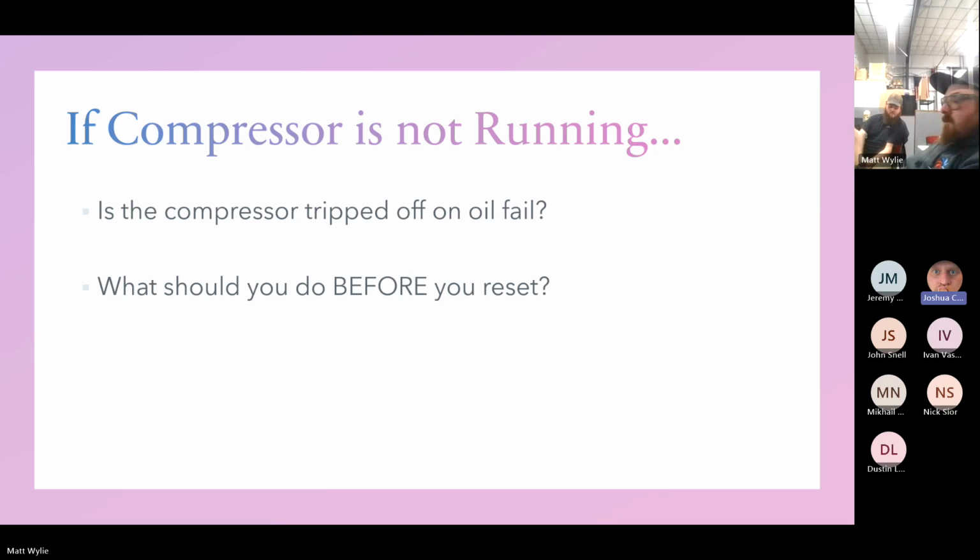It could be the suction screen also, that plugs and the oil can't get back to the compressor. Okay. What about our superheat? How can superheat cause an oil fail? Well, if it's too low, it won't bring it back. Right or wrong? If it's too low, what do you have coming back to the compressor? Liquid.